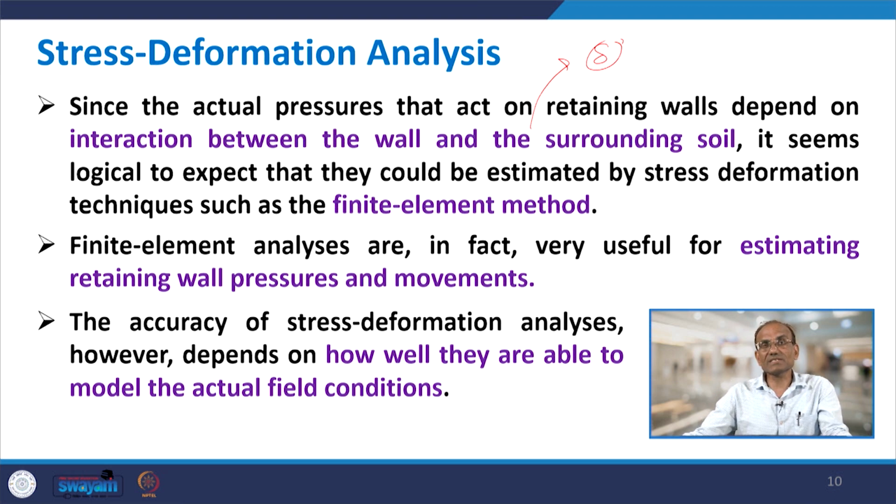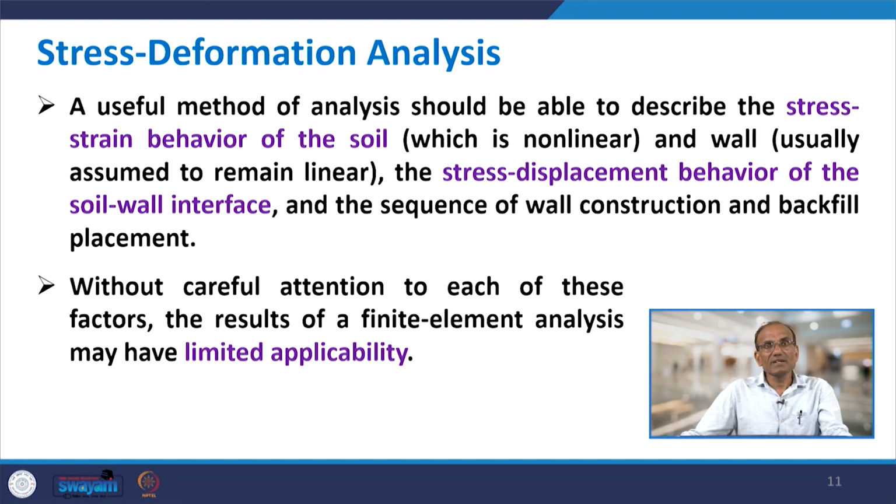The accuracy of stress deformation analysis, however, depends on how well they are able to model the actual field conditions. So, depending on the actual field condition, this can be modeled. A useful method of analysis should be able to describe the stress-strain behavior of the soil, which is nonlinear, and the wall, usually assumed to remain linear, the stress displacement behavior of the soil-wall interface, and the sequence of wall construction and backfill, how it is placed. Without careful attention to each of these factors, the results of finite element analysis may have limited applicability.